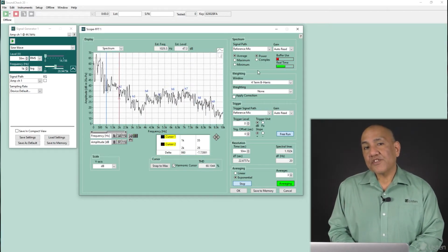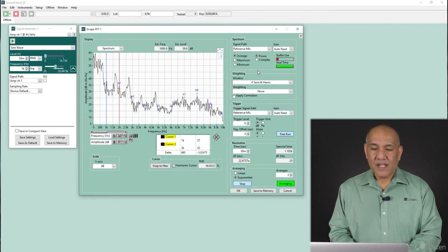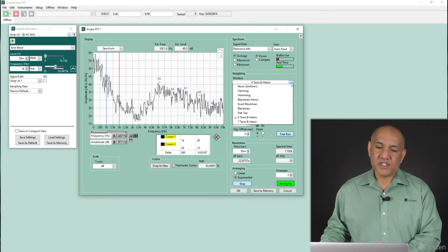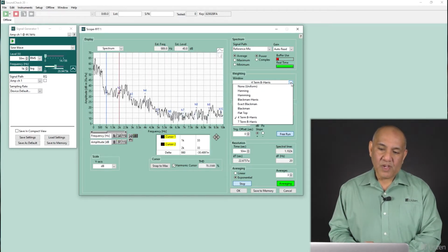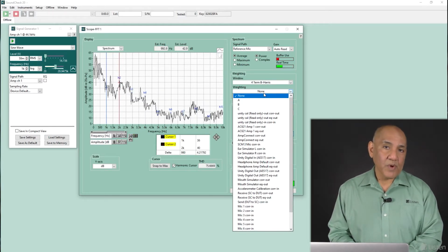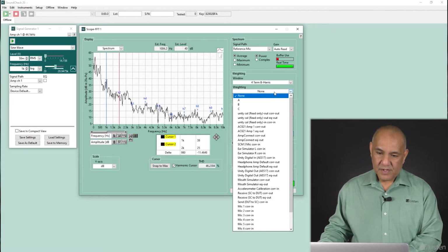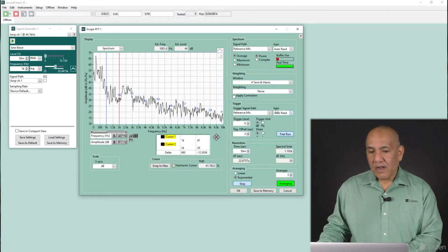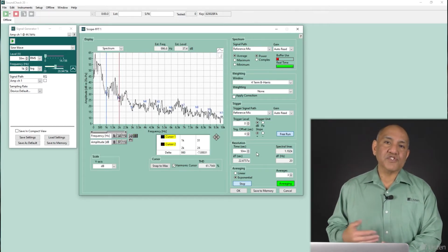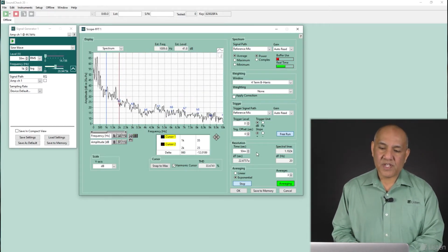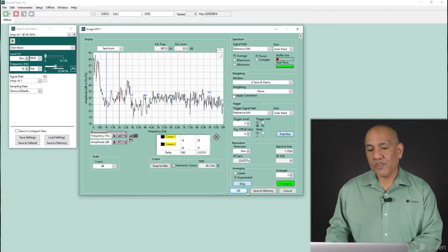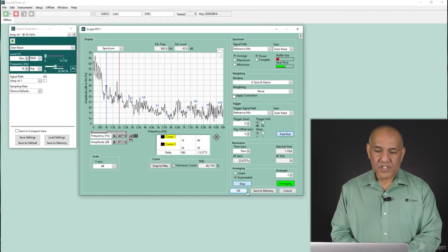The spectrum analyzer uses constant bandwidth FFT analysis. If you look at the right side of this window, I can drop this list and choose the type of windowing I'd like to perform on the measurement. And then below that, I can even apply any type of weighting, A weighting, for example. Okay. Down here, very much like the oscilloscope, I can set some type of input trigger level so the measurement only occurs on an input trigger. And then down here is where I could choose whether I'm doing exponential or linear averaging.